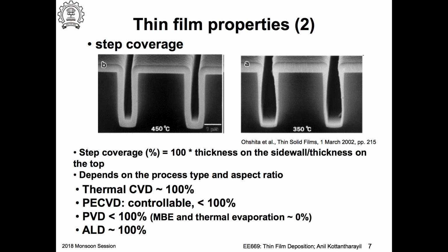There is an initial increase in the series resistance, and at some point it becomes open circuit. Now electromigration will be more severe if my deposition is like this. I need to contact, meaning connect together, 1 billion transistors, and to be sure that it's going to be like this everywhere.